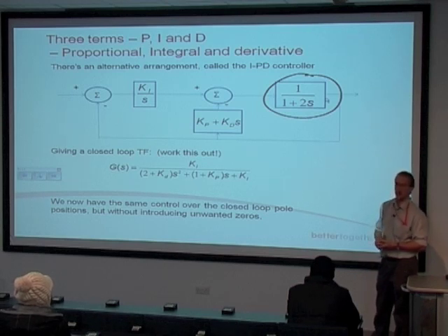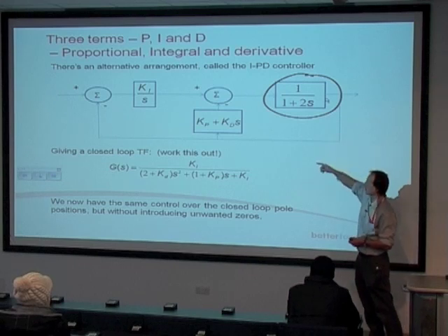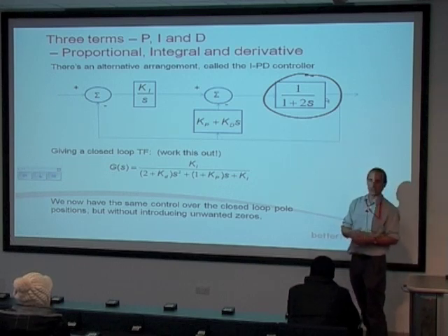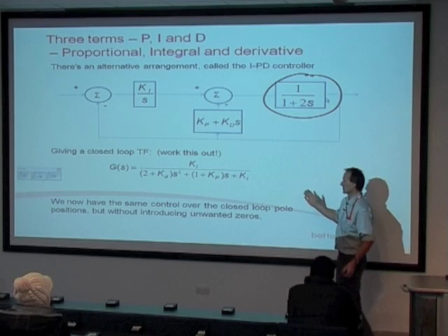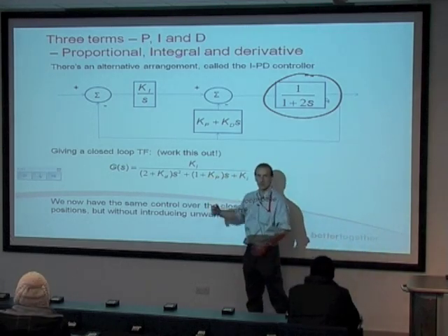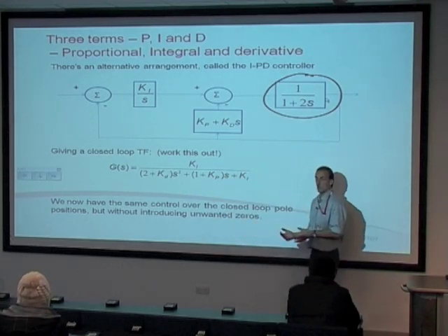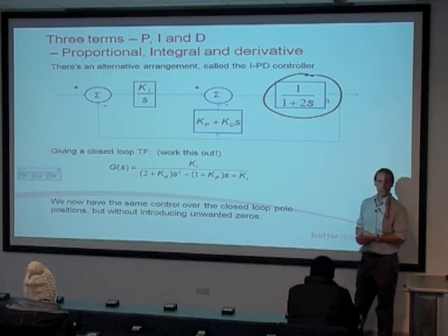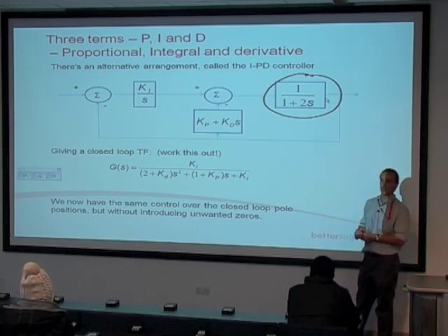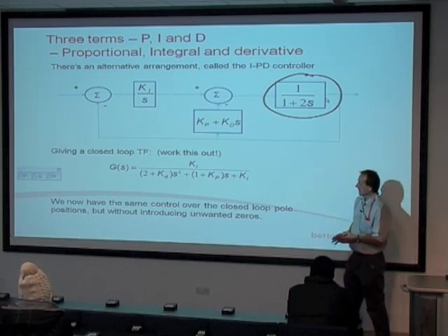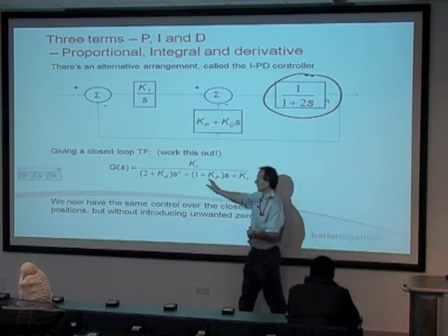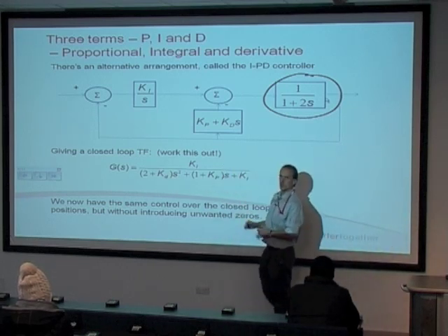Is it going to be a quadratic? No. Because if I've got s cubed up there and an integrator, I'm going to end up with a denominator here that's going to be probably fourth order. Again, if you plow through the block diagram simplification, you'll see that will come out as a much higher order equation. Okay, so I'm going to have a high order denominator, still with a whole bunch of variables in it.